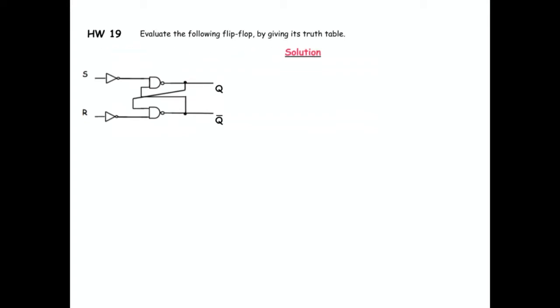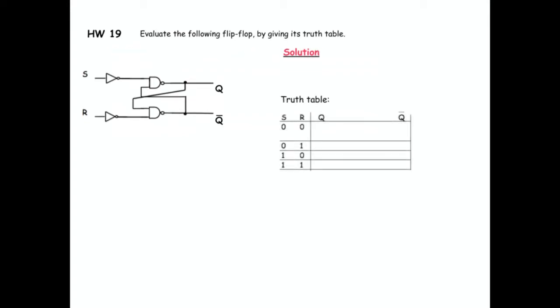Oh, so you're making sure that you don't have the 1-1 condition? Well, yes, that is true indeed, as the previous student said. If they're always complements of each other, I will not get the 1-1 condition, which I definitely don't want. And I'm physically ensuring that it will never happen. I'm also ensuring that 0-0 will not happen, even though previously we allowed for that possibility.